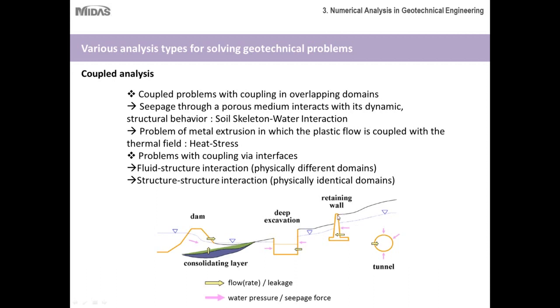For example, the same holds true for this retaining wall. Pore water pressure loads in addition to in situ stress loads or soil loads would need to be modeled on the same retaining wall, as well as this tunnel. So we'll get more and more into detail about coupled analysis later on in this lecture, but that's just a general overview of what coupled analysis is and why it's important. And once again, numerical modeling provides some very unique and powerful solutions for coupled analysis.